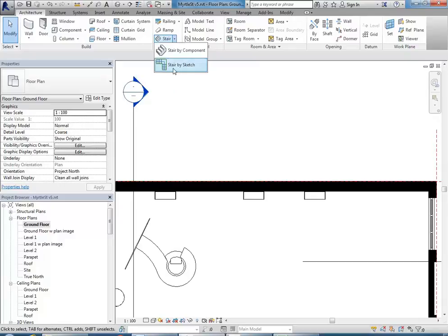And so, when you make stairs, before you even think about using Revit, if you're designing a staircase, what would be the first consideration when you're establishing, say, the number of rises that you need and the overall height of your staircase? So before you worry about the little things like even the width of it, yeah, pretty much, yes, that's right, the floors it's going between. So the whole point of a staircase usually is to go from one floor to another. Right, so you're going from one height to a different height, so you need to establish those two heights. That's your starting point when you're thinking about the way it's going to be designed.